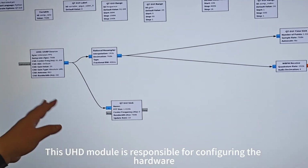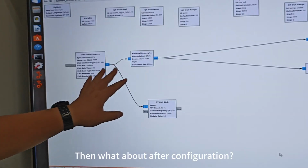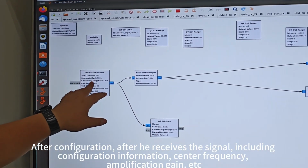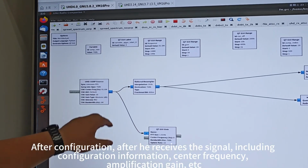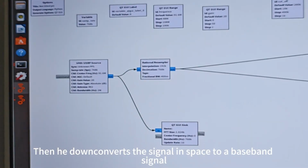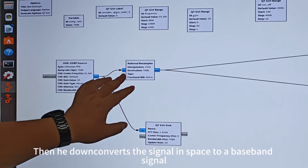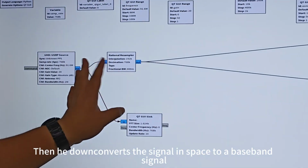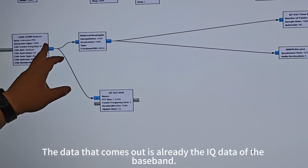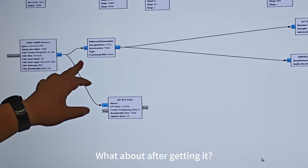This UHD module is responsible for configuring the hardware. After configuration, after it receives the signal, including configuration information, center frequency, amplification gain, etc., it downconverts the signal in space to a baseband signal. After backend processing, IQ data comes out. The data that comes out is already the IQ data of the baseband.